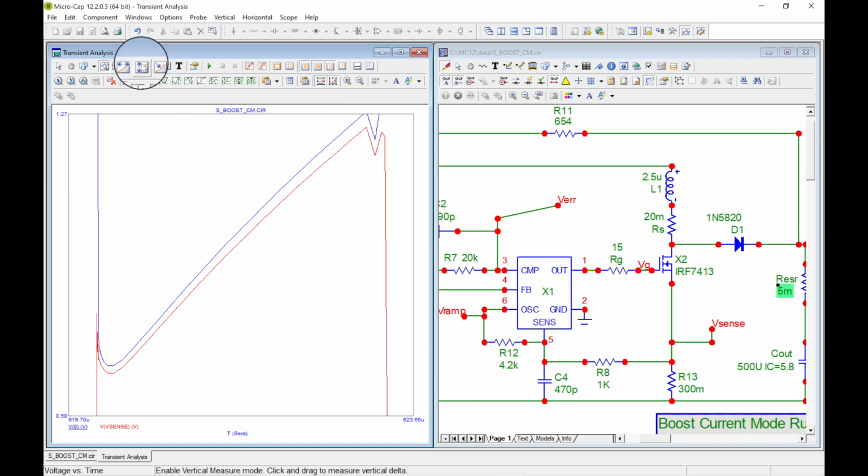If we wanted to measure that, let's see if we can. Let's say right here, from here straight down to here, that's like 38 milli. And if I come right there, well, I went a little bit too far, but it says 24. It's less than that. It's around 20 probably. So there you go, there's two ways to do it. You can also get your cursors over here and do things like that. But okay, I think that's enough to help you get around the circuit.